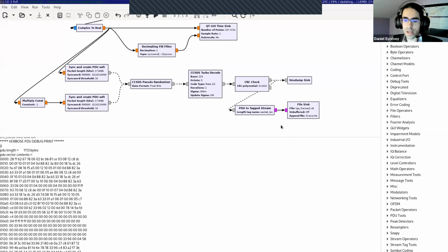Maybe you can think of the Ethernet card on your computer. It has an LED that blinks when you send a packet. But still, on the Ethernet cable, there is this Ethernet signal present all the time, even if you're not sending packets. So this is more or less the same. You have the radio frequency signal, which is present all the time. And when the spacecraft has some data to send, it sends a non-idle frame. When there is no data to be sent, it sends an idle frame, just because frames need to be sent all the time to keep this radio frequency signal active.